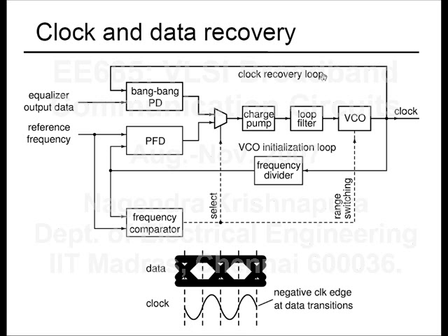The top part of the circuit shows you that it's in slightly thicker lines, I think. But to let it lock, it also has to work over a reasonable range of frequencies. So, what happens is the VCO has multiple capacitors. You can switch in and out capacitors. It's like band tuning on the radio, right? It tunes to different bands. With a single capacitor, you cannot vary the frequency continuously over a wide range. That's why we do this.